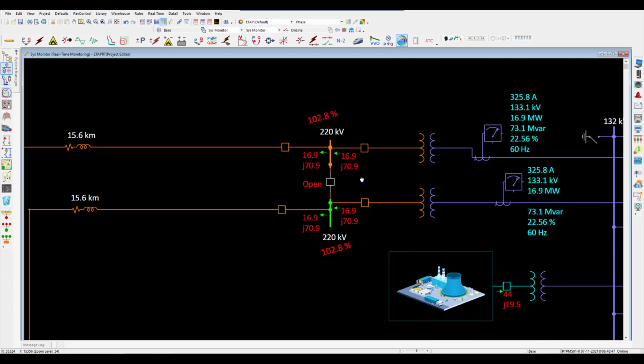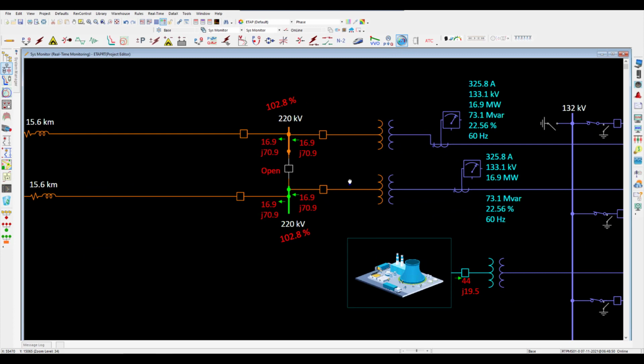The state estimator is essentially not only looking at the meter measurements to analyze the state of the electrical mesh, but it also is doing a load distribution. So you can see the state estimator output all the way down to the last load in the electrical system, all the way from high voltage, medium voltage down to the low voltage circuits.